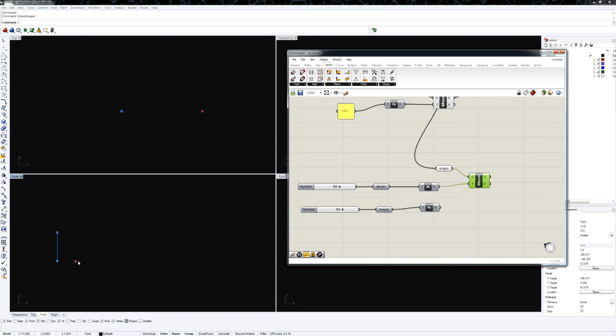So now that I moved it in x, I'm going to take the point that I moved in x, and now I'm going to move it in z. So this controls the z, this controls the x, and I'm just going to turn the preview off on that move, and I'm going to dump this to a point parameter. Maybe I'll turn the preview off and hit the space bar and hit the little blindfold guy, and call that new point.